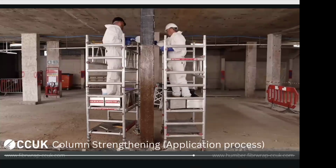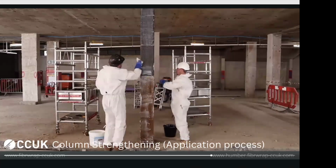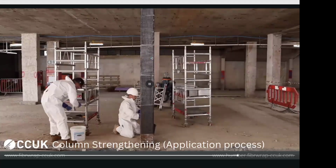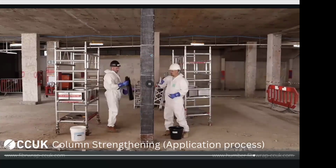Now, in this particular time-lapse video, you could easily see the benefit of using fabric systems on a concrete structure, because it is just a fiber, you could easily wrap it around the column and provide a jacket around it. But if you use plate, obviously you can't do this kind of strengthening with the plates.